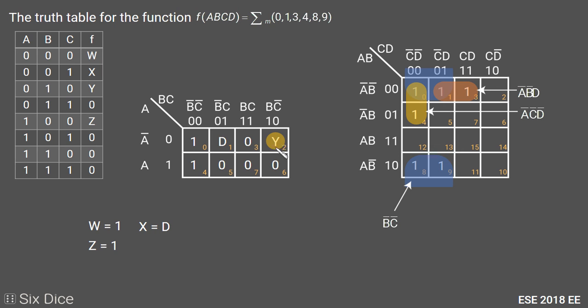So if we put y's value as d bar, then it will satisfy our answer a bar c bar and it will depend on d bar also. If d bar is 1, then this pair will happen, which contains the second cell and zeroth cell, and if d bar is 0, then this pair will not happen and only b c bar will be the answer. So y's value should be d bar here, which is represented as a small d, which is also stated in the question.